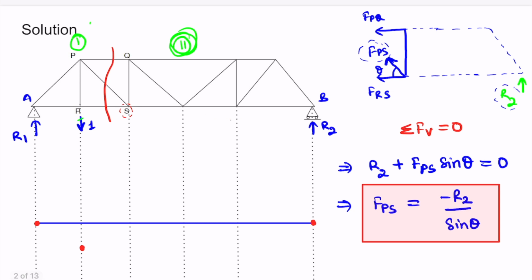Therefore for load location S we can draw it above the baseline and positive. We do not know the exact value here, but we just know that it is positive. Now we can join all the things. We can join it like this, this and this. We do not need to apply the unit load in all these positions, because even if we do that, it will come here and here only somewhat. So we do not need to do that. If we want, we can do that, but there's no need. It's just a waste of time for us.